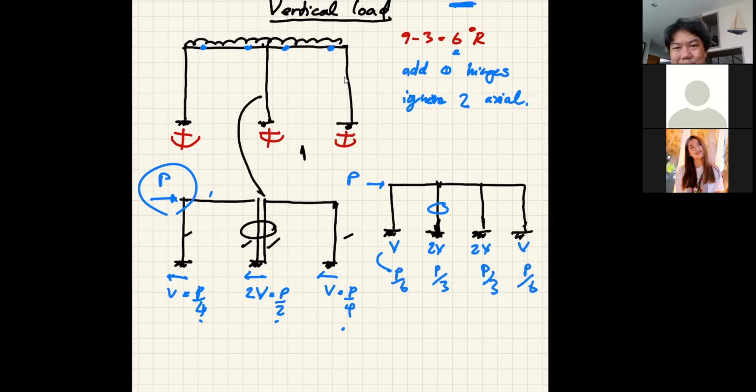But I don't know, because with things like this, there's no right or wrong. But I would rather teach this later, because if you know you can approximate things like this, you probably do worse with the slope deflection and moment distribution, which give you more accurate results. This has limitations. In order for us to do something like this, we assume the stiffness of the columns and beams doesn't matter.